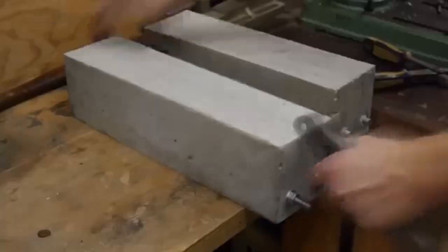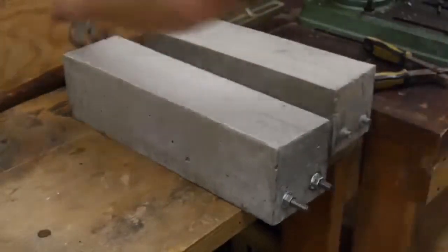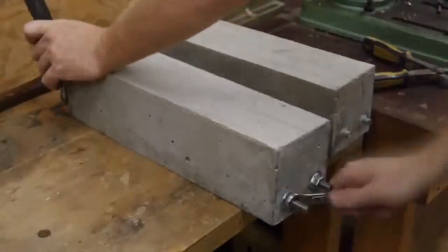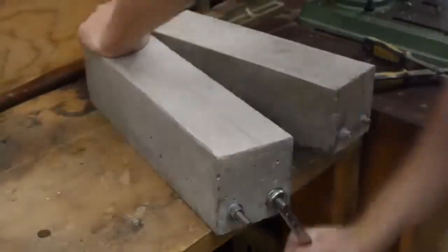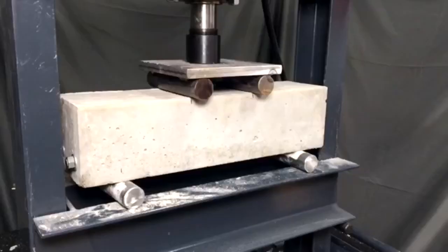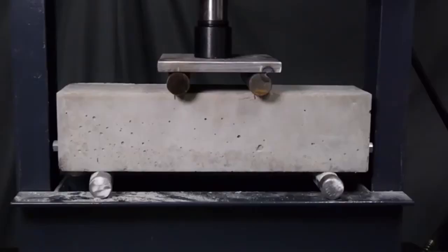The tension already in the steel is able to take up the force of the press without requiring the beam to flex. For the post-tension beam, I inserted the steel reinforcement after the concrete had cured. Then I tightened the bolts on the rods to pre-stress the steel. Under the hydraulic press, the results are nearly identical. The tension in the steel held the beam in compression for much longer than a conventionally reinforced member could. Of course, the cracks eventually appear, but it takes much more force before they do. That's because adding force to the beam isn't necessarily creating tension at the bottom, but simply reducing the compression that's already been introduced through the tension in the steel rods.